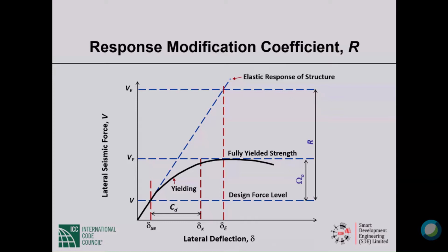If we want to figure out the very largest bending moment that can happen at that support section under the design earthquake, our estimate of that would be omega sub 0 times 100 foot kips. For a special moment frame, omega sub 0 equals 3.